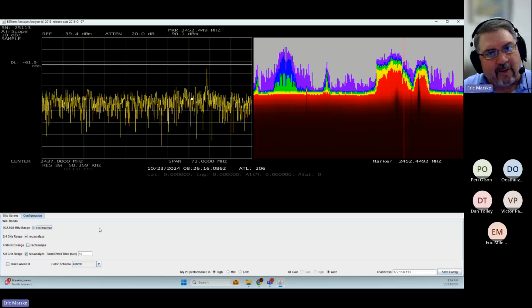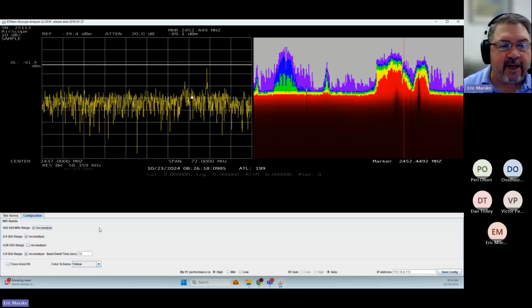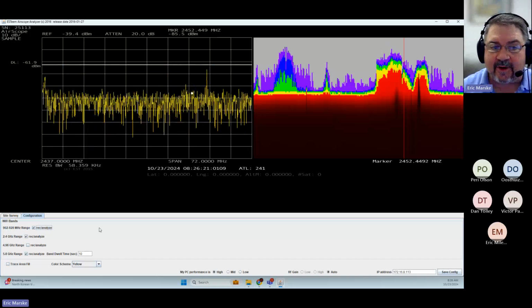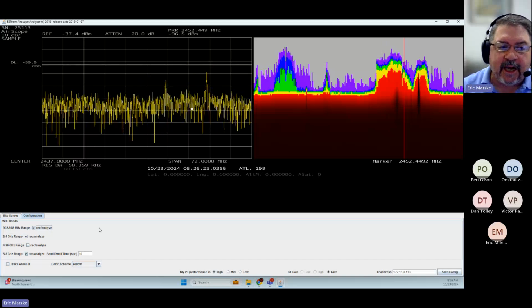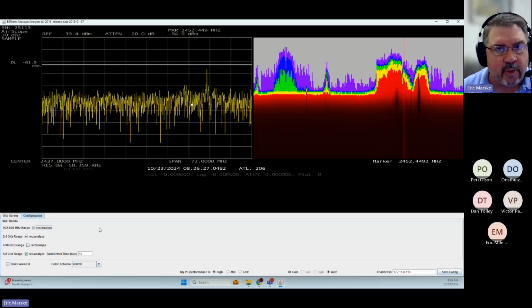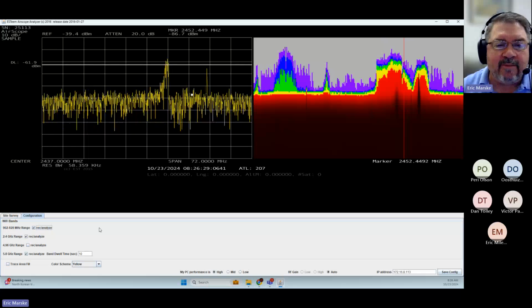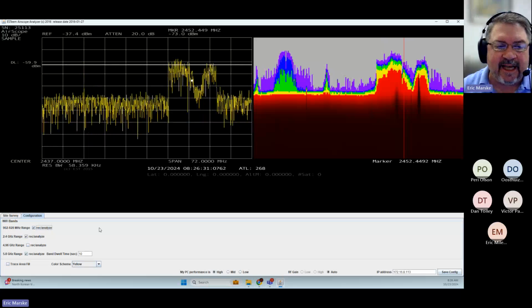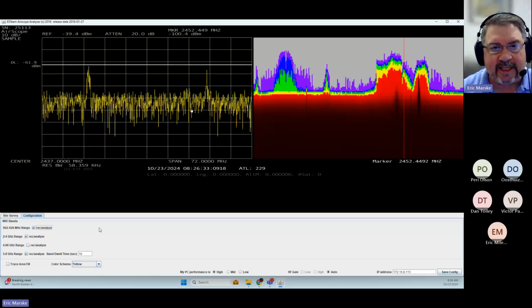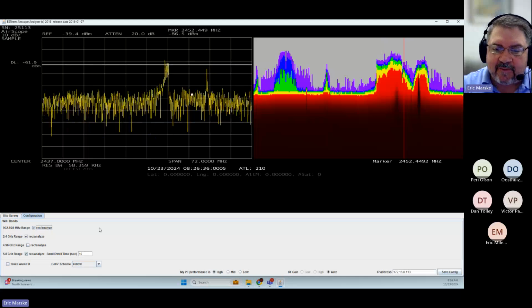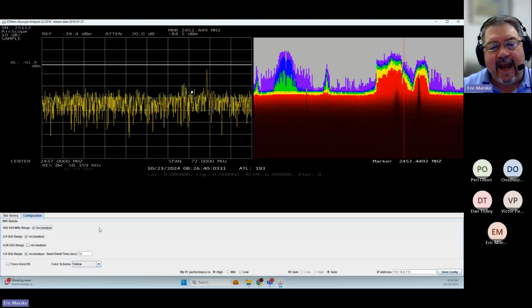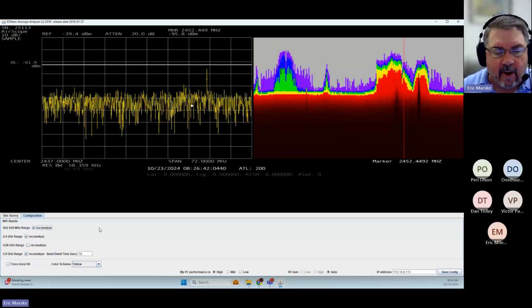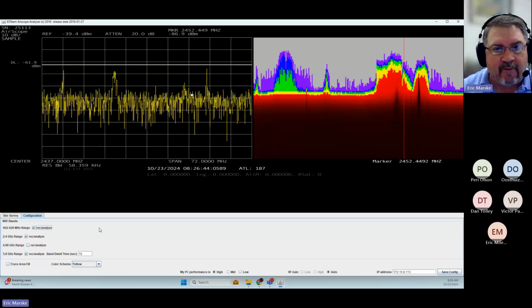So if you're running a single frequency, say you're only interested in the 900 megahertz or the 2.4 gigahertz, what you can do is only check that one band and then increase your dwell time. I found usually when I'm doing field work, I just run this out to say 2 minutes, 120 seconds, because then it'll measure for 2 minutes, start over again, and go for 2 minutes, and add all of these together over time to create this kind of profile map.